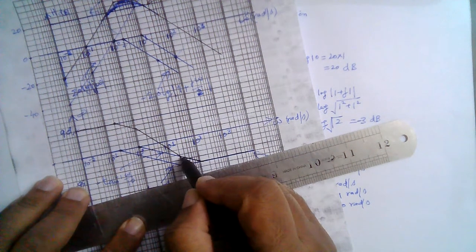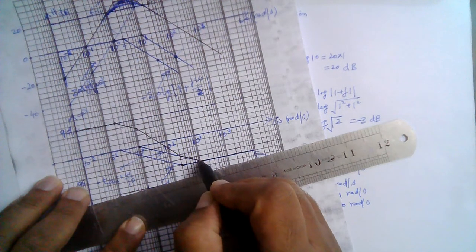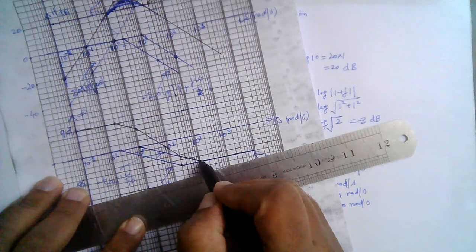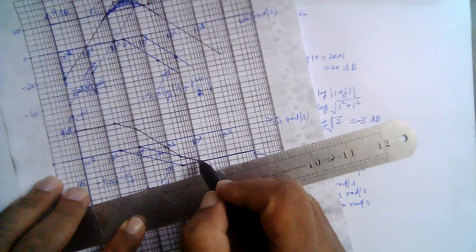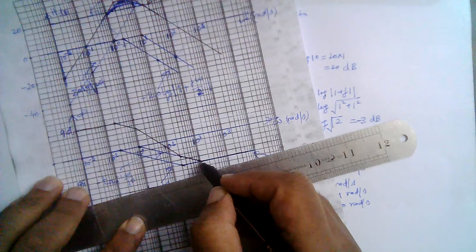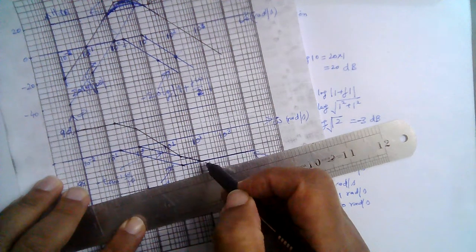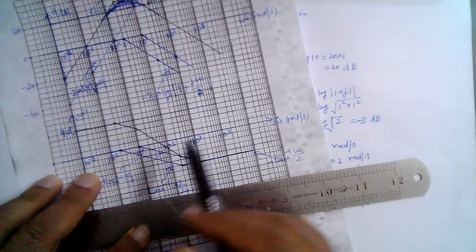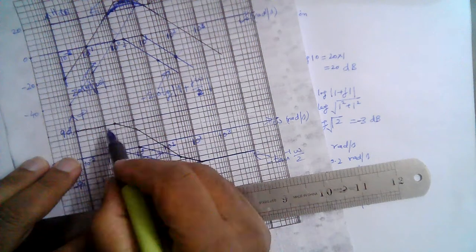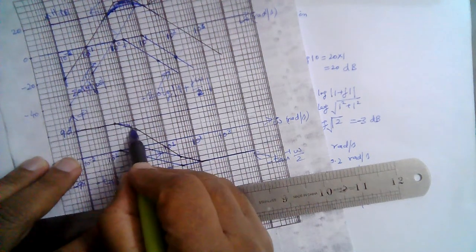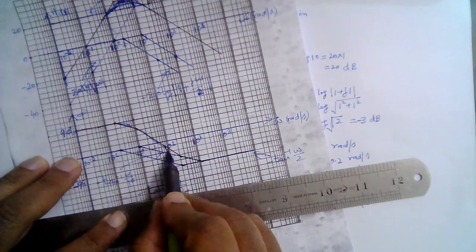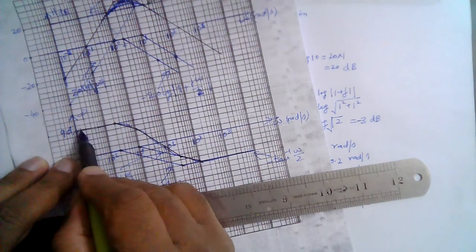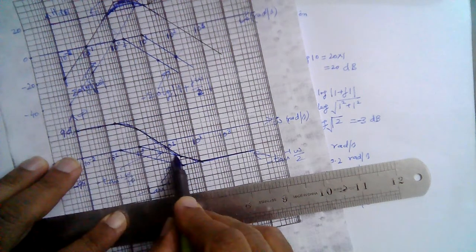So the slope becomes again minus 45 degrees, right? So minus 45 degrees slope, and at this point again we have this term plus 90 and minus 90 and minus 90. So this straightens out at minus 90 degrees. So this is the resultant plot. And this resultant plot is also an approximation. We can apply a correction similar to this one here. So this is again a curve like this. It begins here and then it goes on like this.